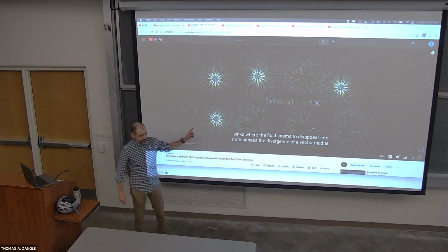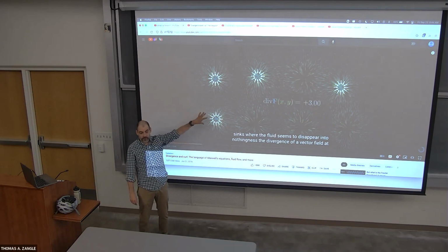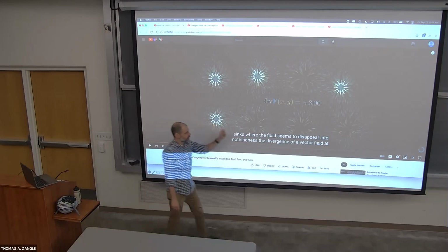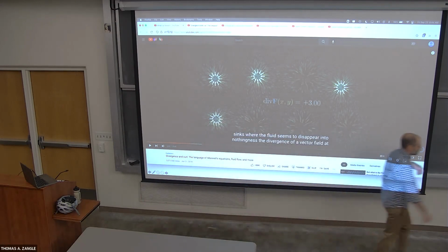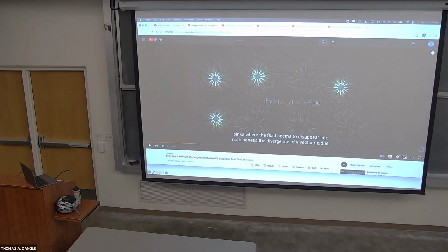I want to be clear, this is an example where del dot v is not zero. Right now we're just introducing the general concept of divergence, so in this example we have not yet forced the constraint of del dot v equals 0. If del dot v is non-zero, then that implies the existence of a source or a sink somewhere. And since in our mass conservation derivation we said mass is conserved, for a fluid with constant density that implies del dot v equals 0, because there are no sources or sinks.